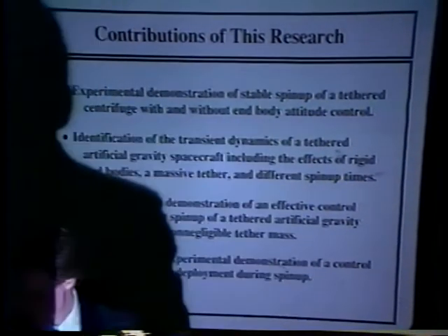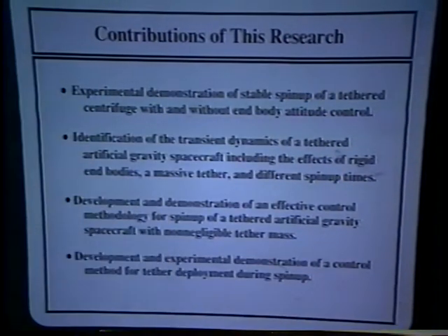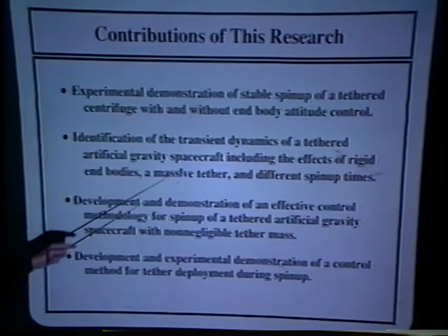The contributions of the research that I've carried out include the following. First of all, the experimental demonstration of stable spin-up of a tethered centrifuge with and without end-body attitude control. Secondly, identification of the transient dynamics of a tethered artificial gravity spacecraft during the spin-up maneuver and immediately following, including the important effects of the rigid end bodies, the massive tether, and also different times taken to spin up to the desired angular rotation rate.